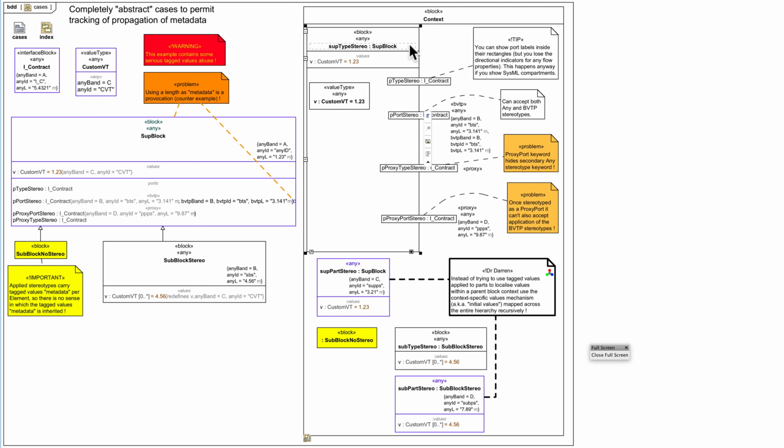So I'm using the SysML values compartment here. If it's not available, you use enable parts compartments, but in fact it shows SysML compartments. So we can show on there values and other aspects of the underlying classifier. I've also shown this value with its default value as a symbol in the structure compartment.